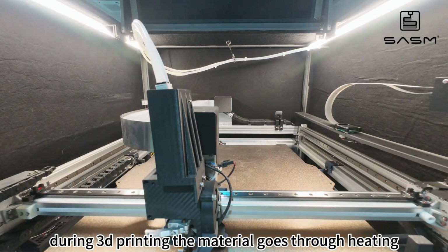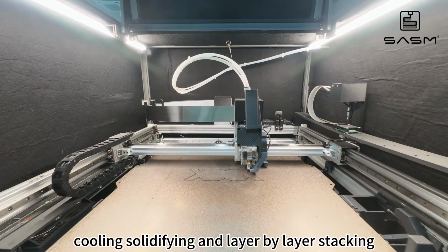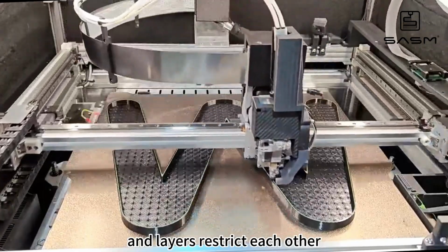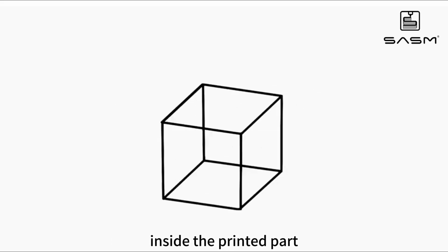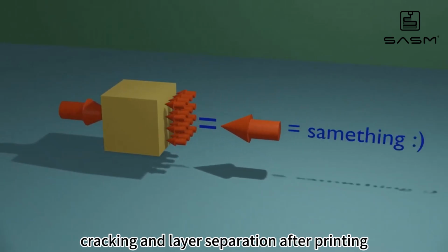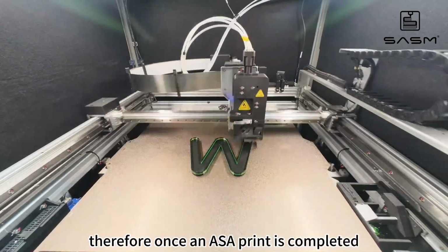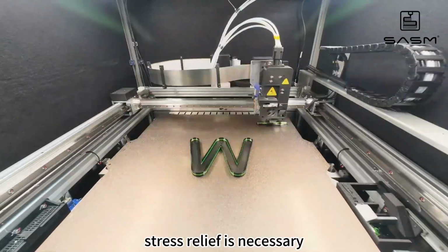During 3D printing, the material goes through heating, melting, cooling, solidifying, and layer-by-layer stacking. Because temperature changes are uneven and layers restrict each other, an internal pulling force is formed inside the printed part. This force is called stress. Stress is the main cause of warping, cracking, and layer separation after printing. This effect is more obvious in ASA filament. Therefore, once an ASA print is completed, stress relief is necessary.